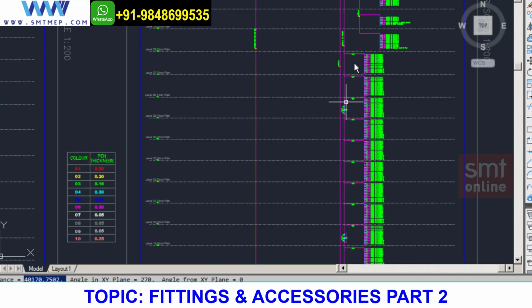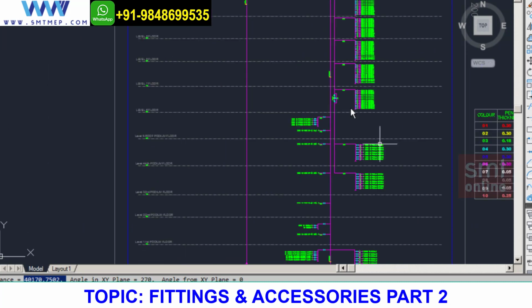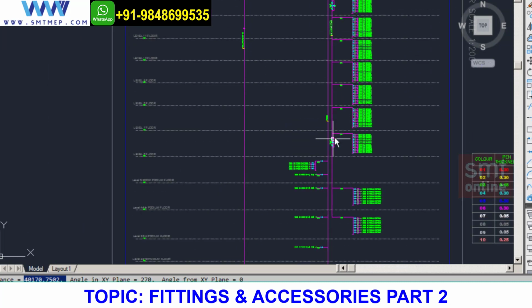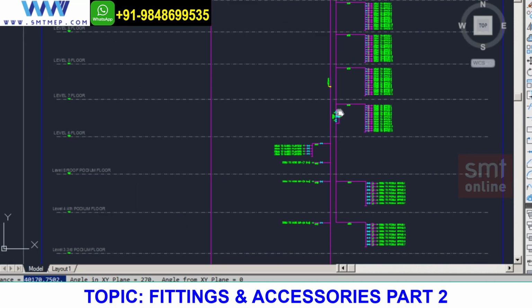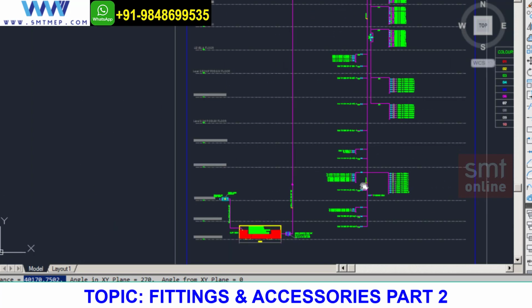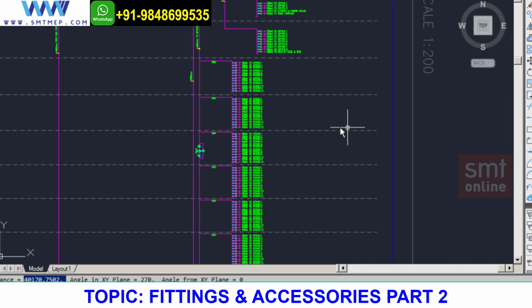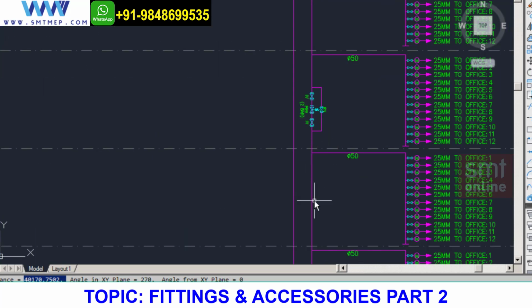Yes, for sure. When it is on the 6th floor, I'm getting this much. I'll be having one more PRV over here. Not only one more, I am having a total of 4 PRVs in the complete project. From here, I can say from the 6th floor to the basement, I'm not having any PRV because it's not exceeding more than 60 PSI, or 60 is also accepted. They have taken it as a safety factor. They might have installed one here also, but I think if they were calculating over here, it might be increasing more than 64, 61, 62. That's why they have installed it on this floor.